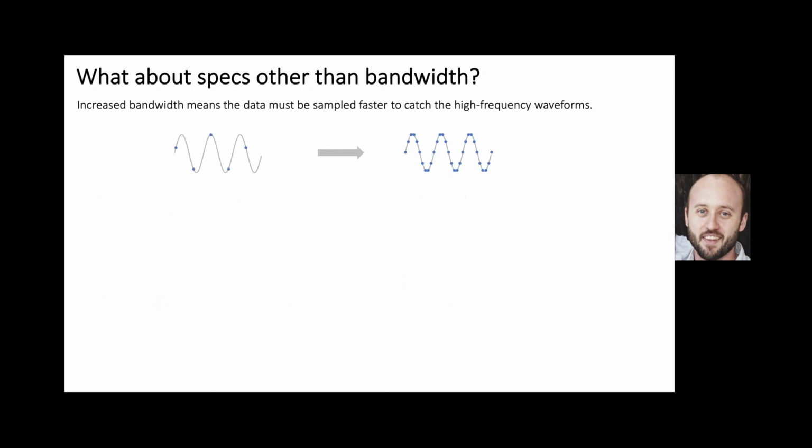So for your reference, if you're looking at an accelerometer spec sheet, like I said, the most important thing is bandwidth. And if you look at the specifications for a piece of hardware, all of the specifications and their performance are really built around supporting higher bandwidth pieces of instrumentation. So if you're able to detect higher frequencies mechanically, you also want to collect data at a higher rate. So this would be what we call sampling rate. So if we have high bandwidth accelerometers, we also want to see high sampling rates to support them.